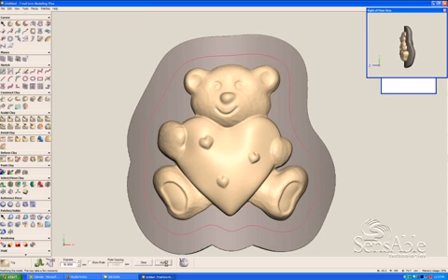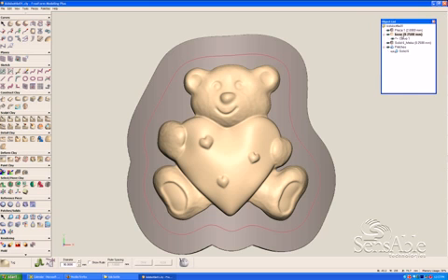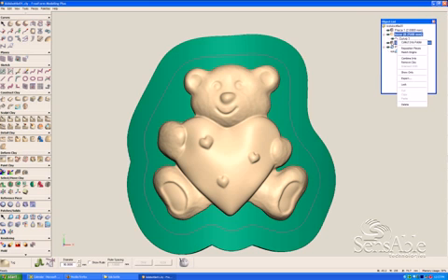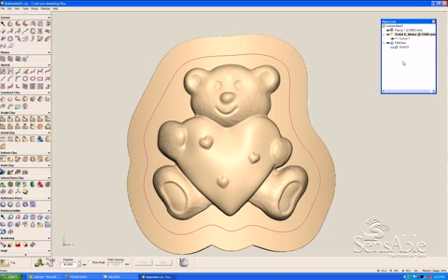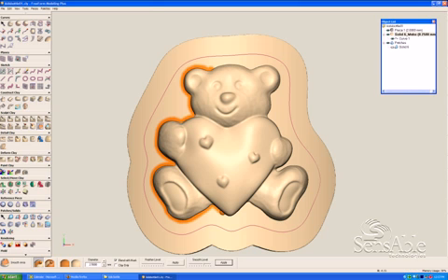Once we've done that, we want to combine the thickened part into the design of the bear so that we have one piece. We can do that easily through the Combine into Boolean technique on the object list. That's a very simple function in Freeform, as opposed to doing Booleaning and shelling and things like that in CAD, which can be very difficult and frustrating because of the innate problems with those types of functions with surface and solid data. But since we're working with a completely different geometry called voxels, those types of functions work very well in Freeform.